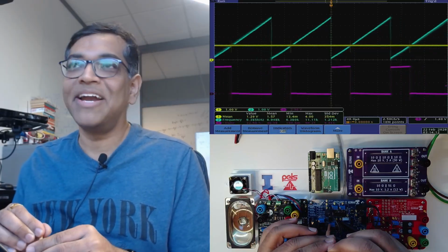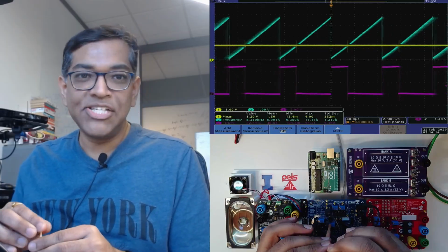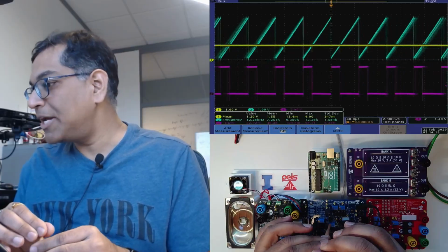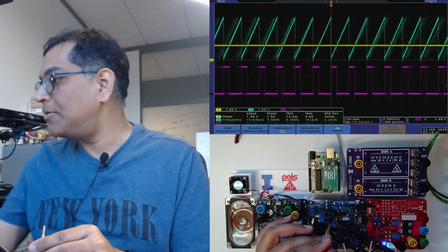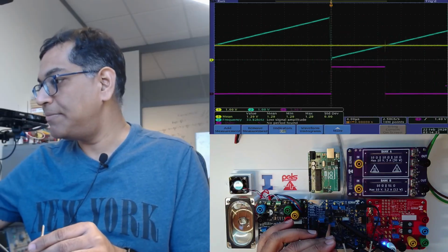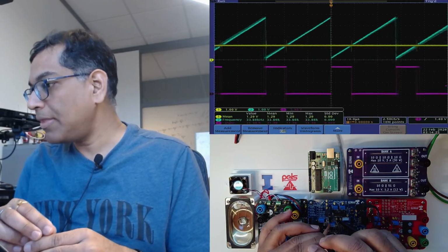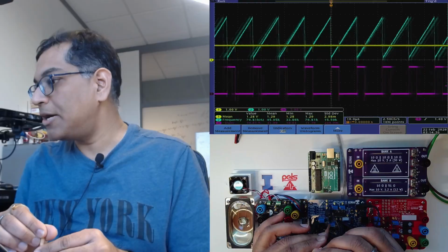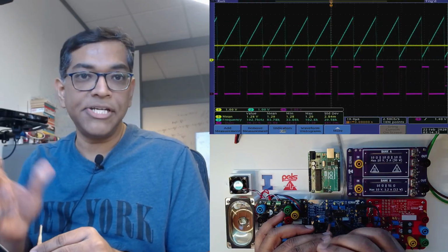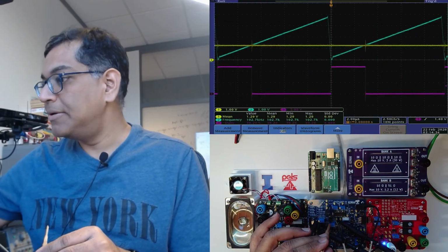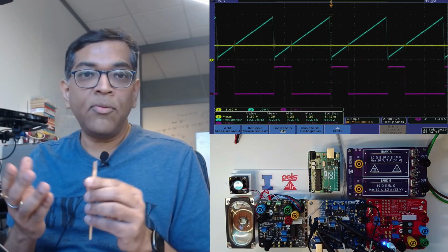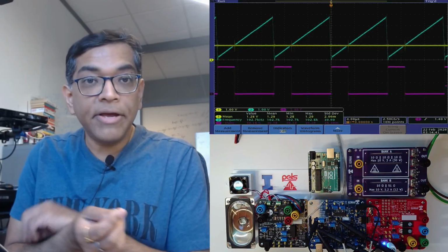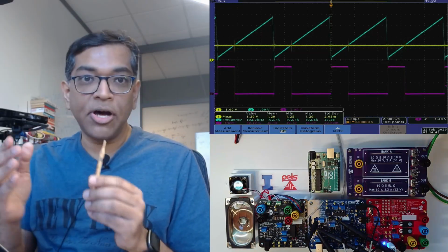We obviously don't run our converter these days at 6 kilohertz. So imagine I want to go to 100 kilohertz. I need to change my frequency in this case to 100 kilohertz. Let's see if I can zoom in. So roughly we are talking about 100 kilohertz. Now here we are at 100 kilohertz switching frequency, roughly speaking. Now how cleanly we have generated the blue waveform becomes important,